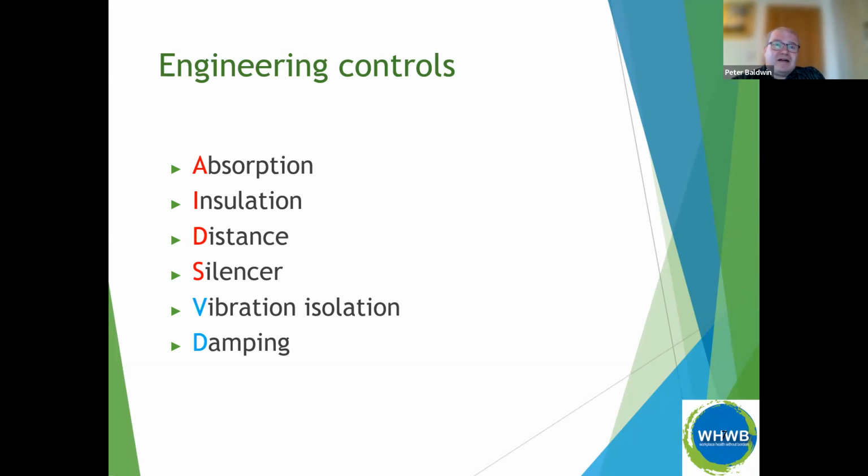Distance. As a rule, the noise levels will fall as 1 over the distance squared. So if we're doubling the distance, you quarter the amount of noise. However, distance doesn't quite work like that, because there are other sound sources going on there. As I said, reflections, reflected off surfaces, etc. So it's not quite this inverse square law. But generally speaking, the further you are away from the noise, the more noise reduction you do get.